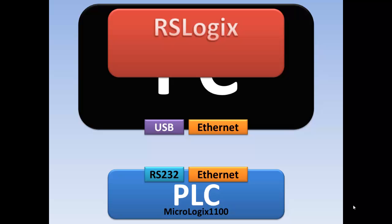And if you go to the PLCprofessor.com website, go to useful links, you can find a link to purchase a USB adapter and cable, PM02 type cable, to connect between the USB connector on your PC and the RS-232 connector on the PLC. Now the RS-232 connector on the PLC, it is not a 9-pin sub-D shell. It is a round DIN connector. So you do have to have a semi-special cable.